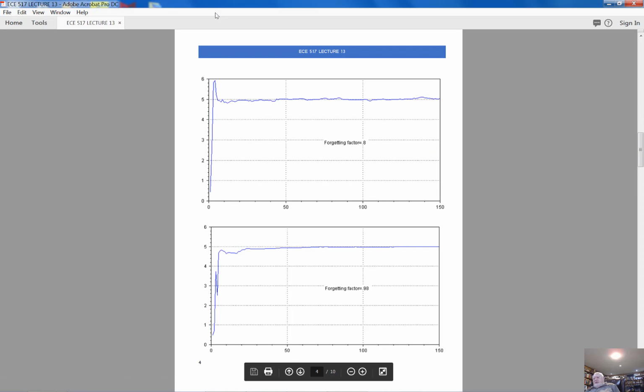The next, what you can see, is a situation when the effect of noise is quite reduced. The memory of the procedure is 1 divided by 1 minus 0.8, which is 5, which means that each of these estimates is based primarily on the 5 input-output measurements. So we're getting the effect of averaging out noise, because now the averaging is performed on 5 observations.